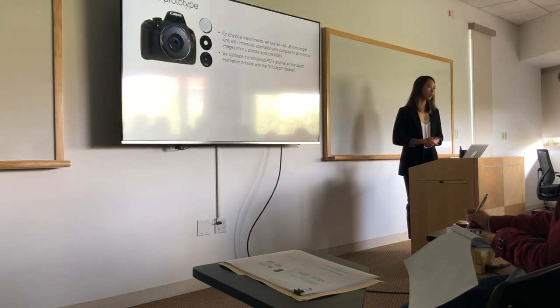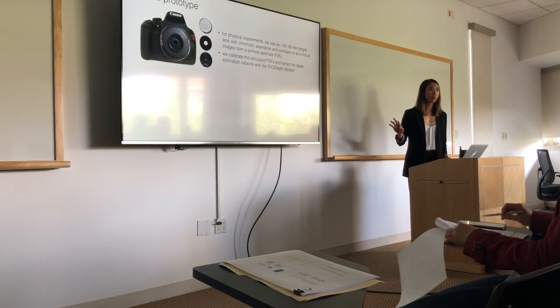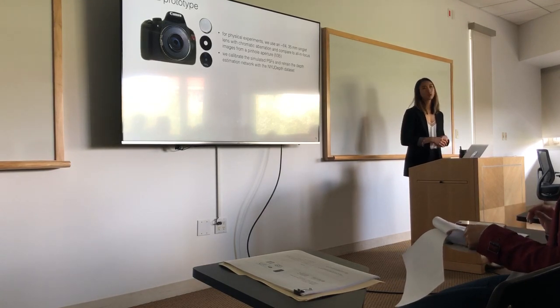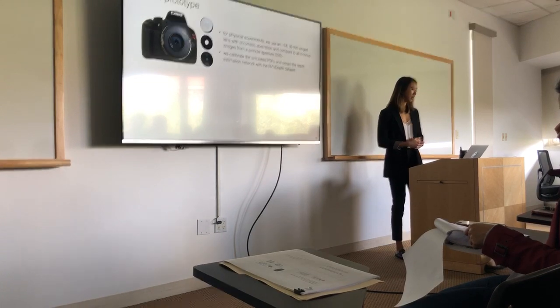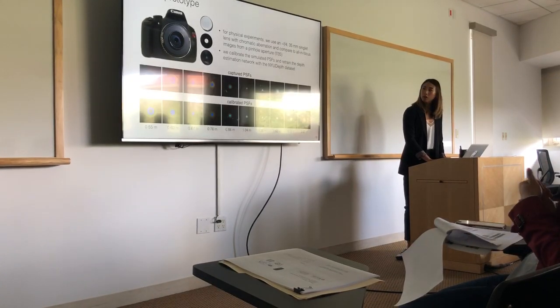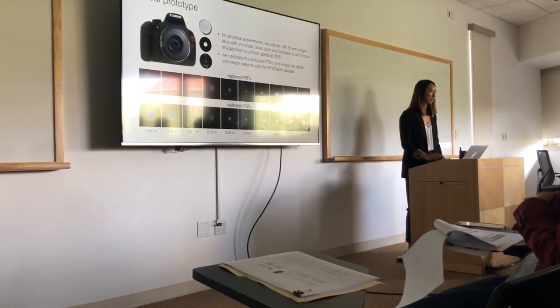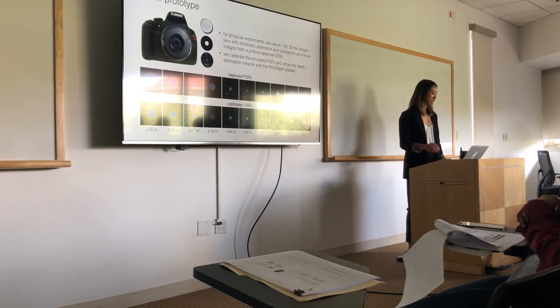From our simulations on depth estimation, we're going to move on to our experiments. We make an optical prototype, but we're just going to use a lens with chromatic aberration instead of actually fabricating the fully optimizable lens, since in the previous project we already showed we can do that. What I need to do here is to calibrate the PSFs from our simulations with the actual PSFs of the camera, and then retrain the depth estimation network for that specific camera.